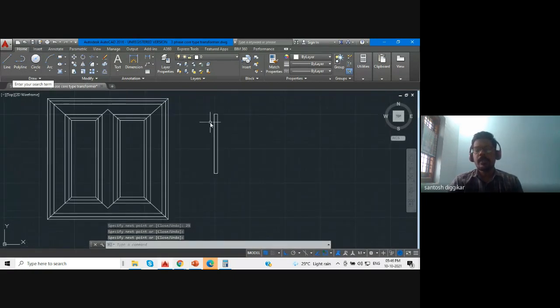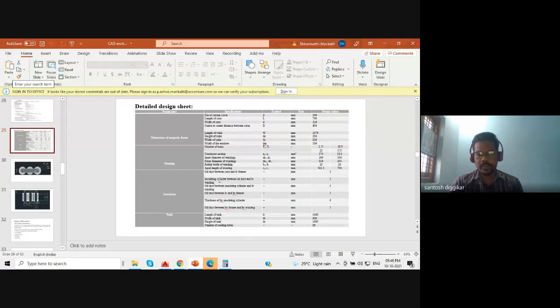And between the LV winding and core we have an insulation. So after the LV winding, you can see from the table, we have an insulation of 5. Then there is an oil duct of 5 mm. Then there is an insulation cylinder. Then there is a 5 mm.